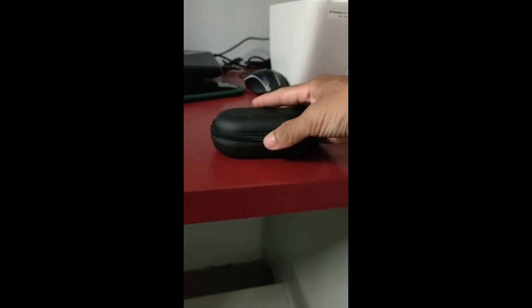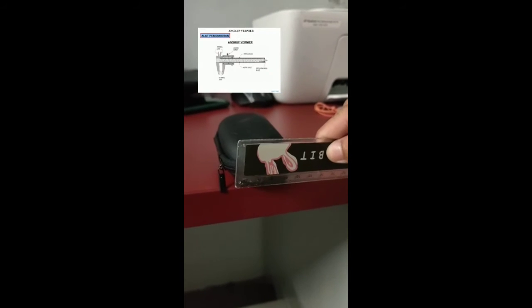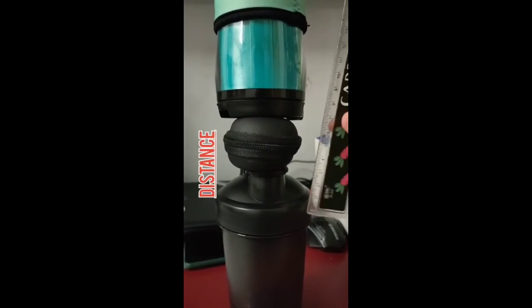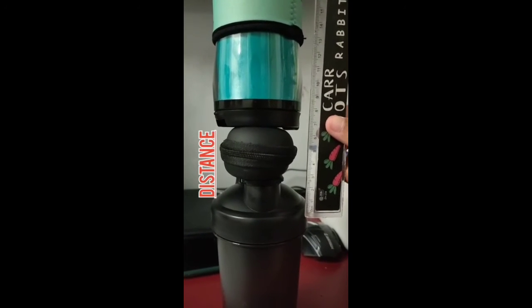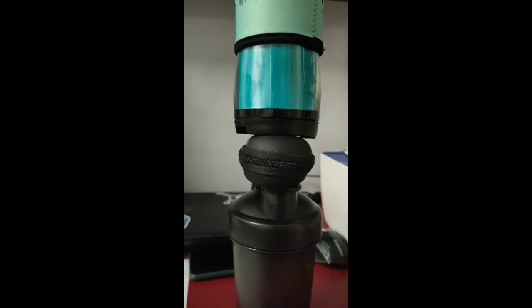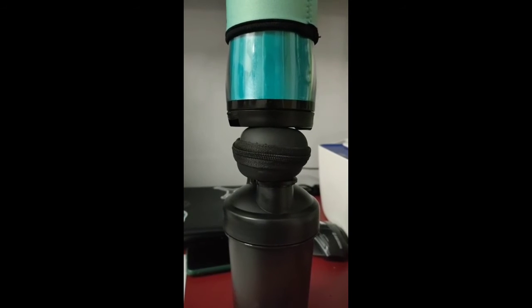Using the vernier caliper, measure the length of the specimen, width 1 and width 2, and also the depth of the specimen, and then record them. Place the specimen between the two platens and then measure the contact point distance. Apply the load to the specimen and then record the load at which the specimen fails, within 10 to 60 seconds. Finally, repeat the steps using different specimens.